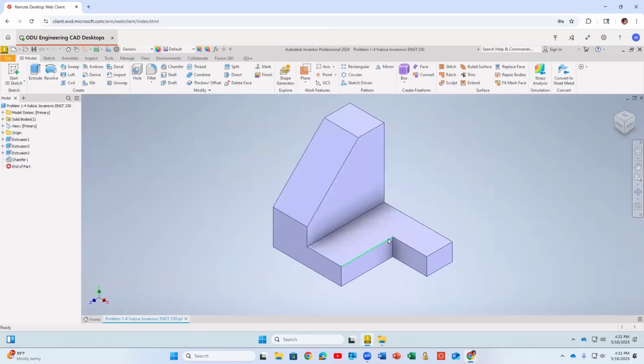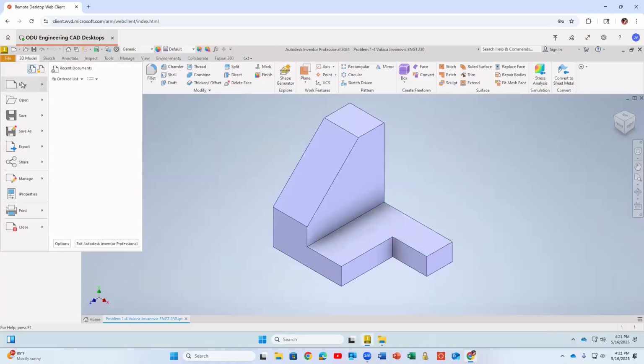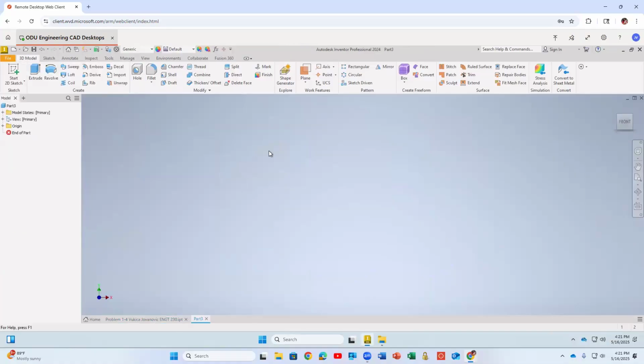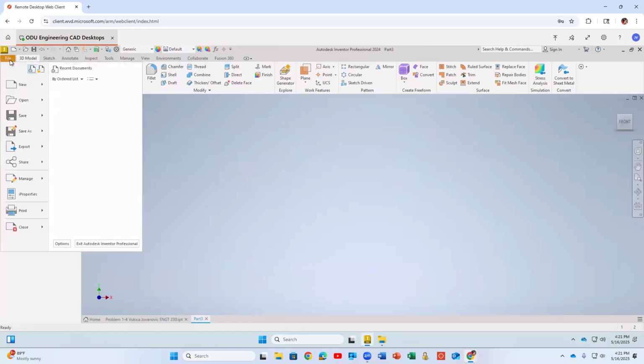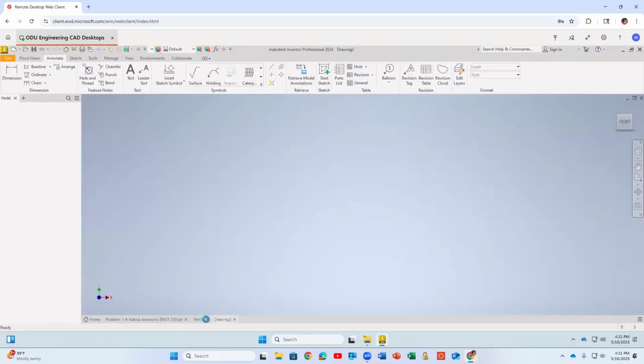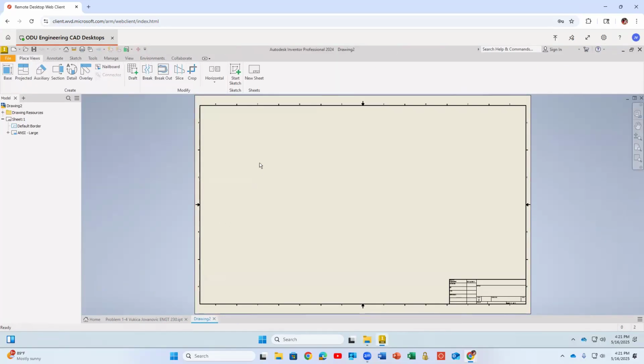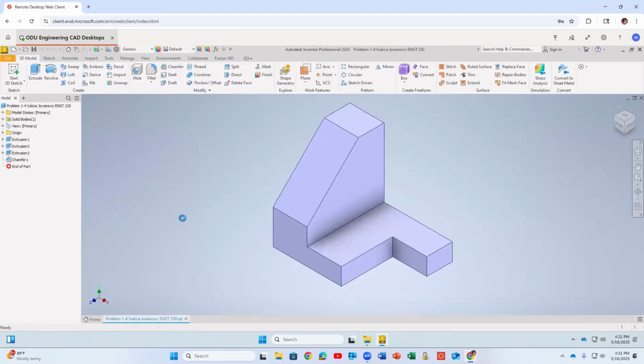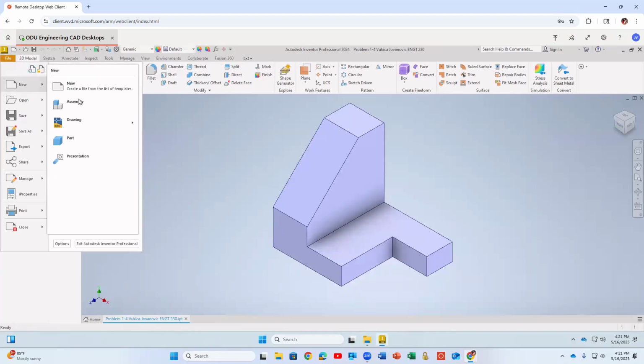There you go. So, and I can also go here, create another part. So, oh, I'm sorry, I didn't want to make another part. I want to make a new file, new drawing. And again, it will give me that big drawing. So I want to make it smaller. So yeah, this is the one that I want. So it now, you see, it doesn't know that I want to make it from this. So I'm going back to my part and I select this in the tree. And from there, I want to say, create me a new drawing.